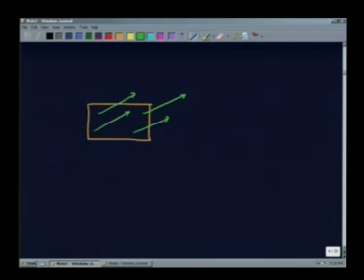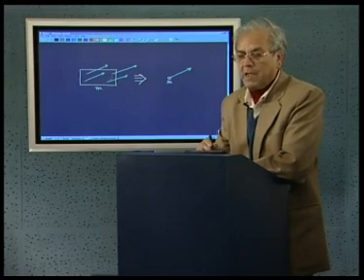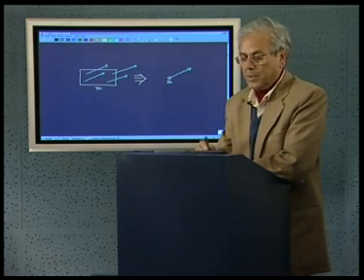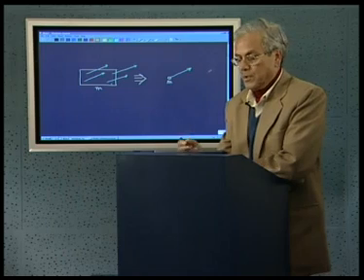So, effectively, this is more or less equivalent to a particle with the same velocity or displacement as this rigid body, but the total mass of the particle is the same as the mass of the body. So, in cases of pure translation, a rigid body may be considered to be concentrated in a particle with the same displacement parameters, velocities and acceleration.